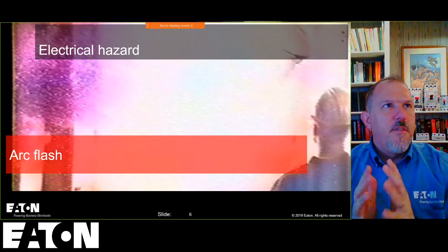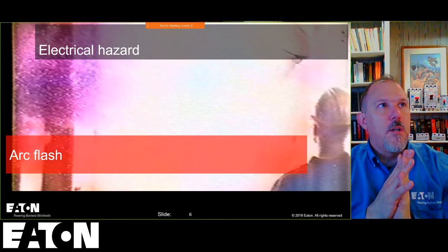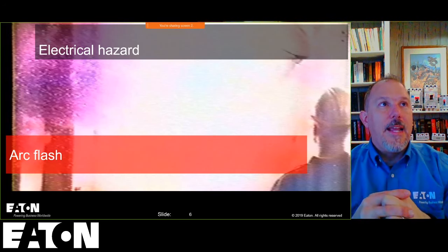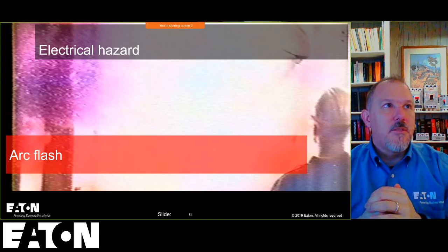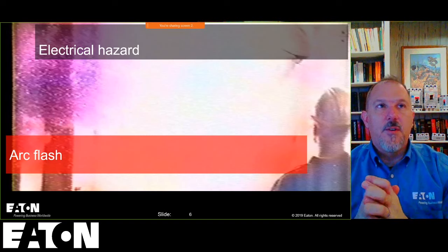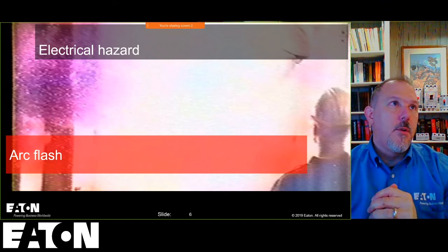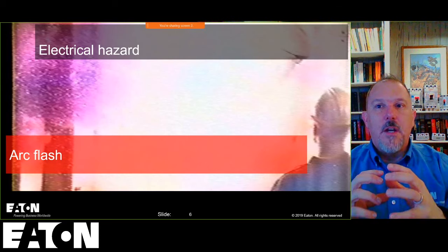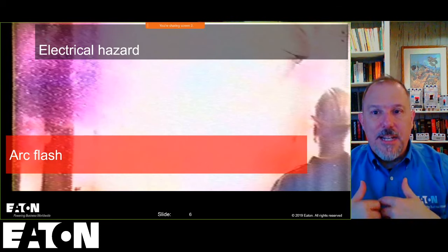Marcy says the available fault current for the specific site was requested for the installed transformer. Smaller electrical cooperatives will provide infinite bus, acting as though they are providing as requested. Typically, the smaller electrical cooperatives have to pay an engineering firm for the calculation, which they try to avoid. That's a very good point, Marcy. And that's why you really have to understand the data that you're getting.